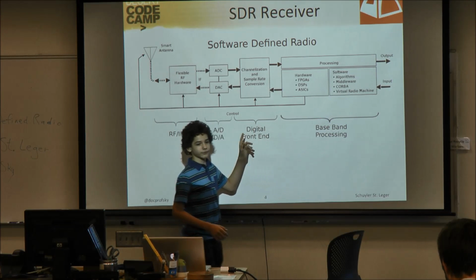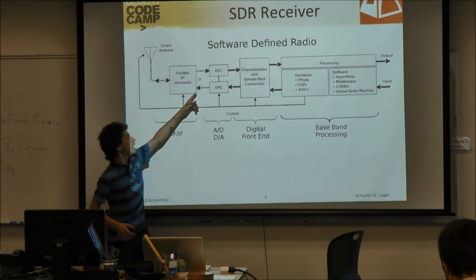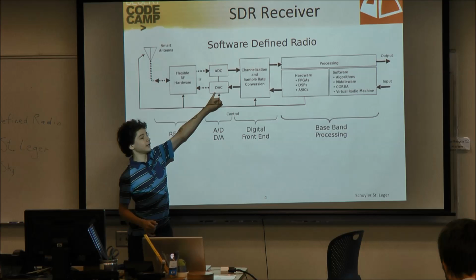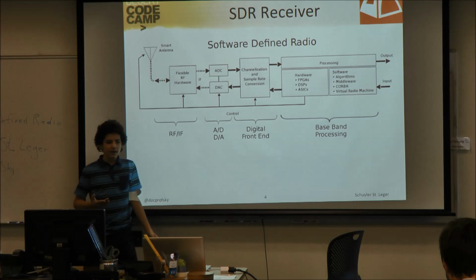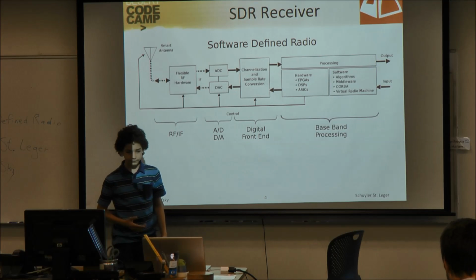Now, one of the things with software-defined radio is if you're operating at a higher sample rate, so your ADC, and if you can transmit your DAC, is running faster, then you're going to need a more powerful computer to handle all of those samples.